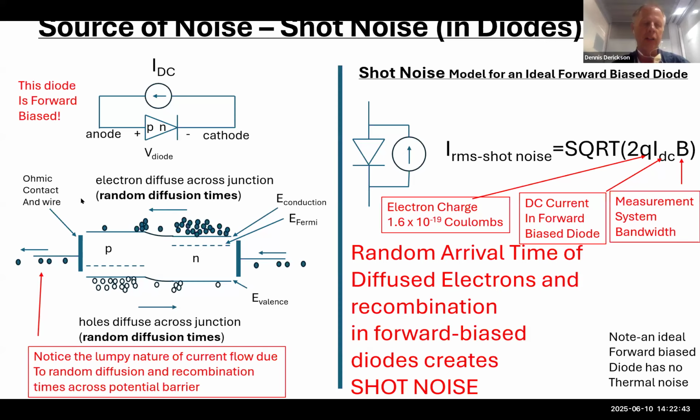And when we're forward biased, this potential barrier is quite small. On this axis we have electron energy, and on this axis we have position. The potential barrier is slightly increased, but many of these electrons have enough energy to surmount that barrier and be diffused and emitted across it. Now, it's interesting, an electron on the right-hand side is a majority carrier, and they live a happy life.